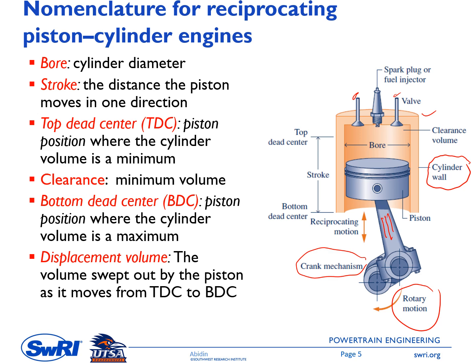And then as the piston approaches the top center, either the fuel is injected if it is a diesel engine, or the spark plug ignites, then it will initiate the combustion. Okay. And then the piston moves down again, the chamber volume increases, and this is the third stroke, which is called the expansion stroke or the power stroke.